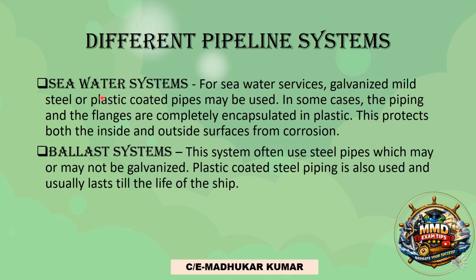Different pipeline systems, like the seawater pipeline, use galvanized mild steel, plastic coated pipes, or rubber coated pipes. In fact, I have seen the piping and flanges completely encapsulated in plastic. This protects both from inside and outside.